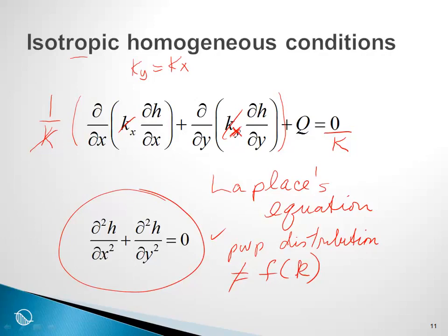And many times, for example, the flow under a cutoff wall, the pressure distribution that we obtain is not dependent on the conductivity that we specify. This is a very useful observation, and we do not need to spend a lot of time refining the conductivity we use for an analysis if we are interested in pore pressure distribution.